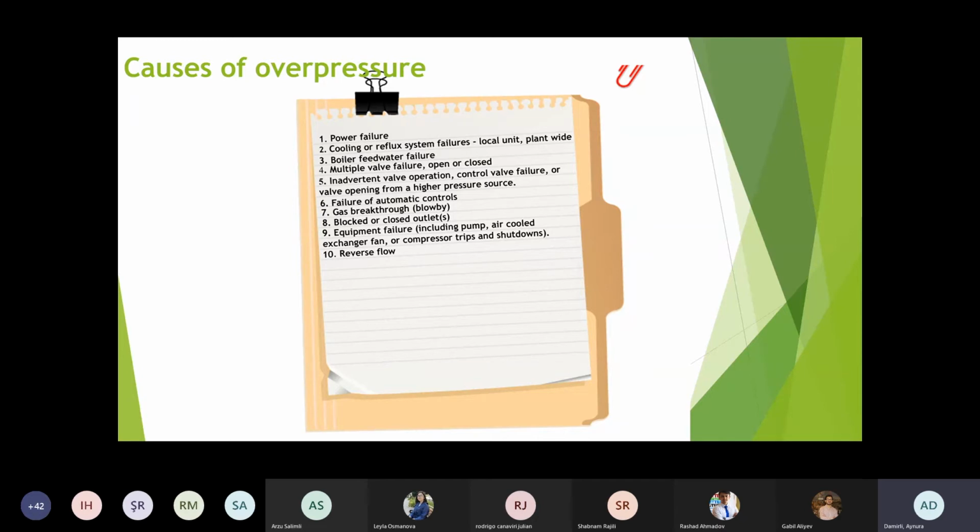If a single check valve is used on the discharge stream, full backflow shall be considered, and the settle out pressure should be appropriately defined. Typically, a dynamic analysis of the process system is required to evaluate a settle out case.